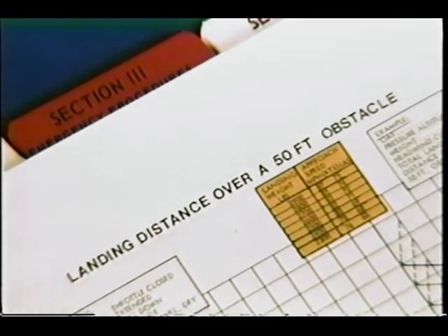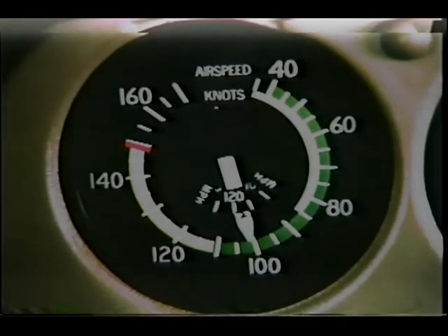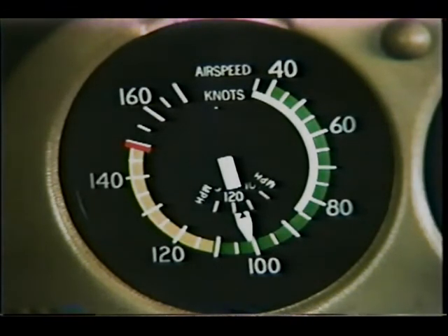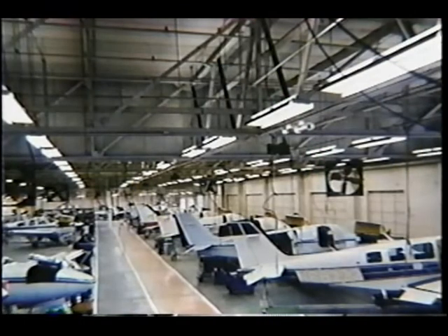Incidentally, were you aware of the fact that some general aviation airplanes have the color-coded arcs on their airspeed indicators painted in calibrated airspeed values, while others display only indicated airspeeds? It's a fact. You see, starting in the latter half of the 1970s, most aircraft were built with airspeed indicators that had color-coded arcs marked in indicated airspeed rather than in calibrated airspeed.